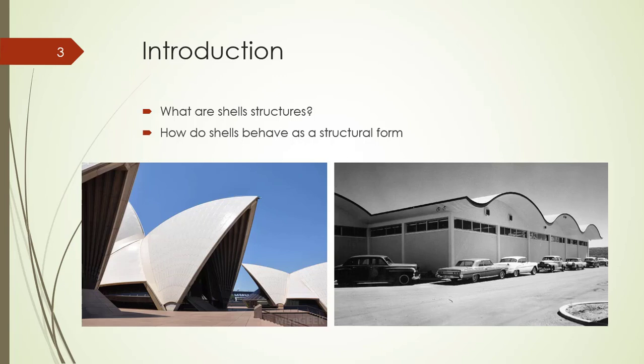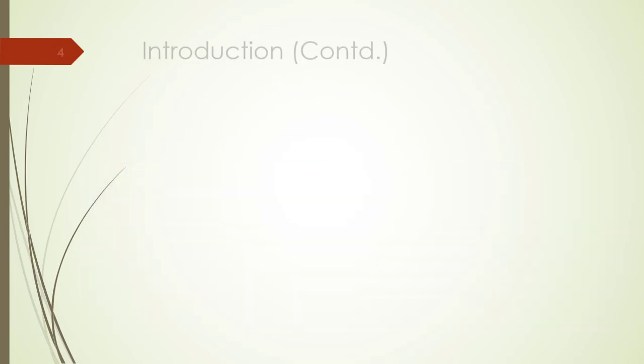The effort in design is to make the shell as thin as practical requirements will permit, so that the dead weight is reduced and the structure functions as a membrane free from large bending stresses. By this means, a minimum of material is used to the maximum structural advantage.